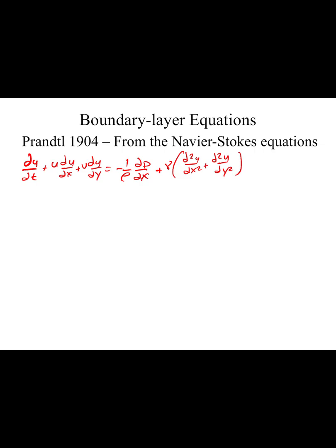As I said, we have a time-dependent term. We have terms associated with our inertia here on the left-hand side. This whole thing is like Dv Dt, or our big Du Dt, going back to thinking about Eulerian and Lagrangian descriptions. So we have our inertial terms on the left-hand side, then we have a pressure term and a viscous term. Those are the balances that we're focused on.